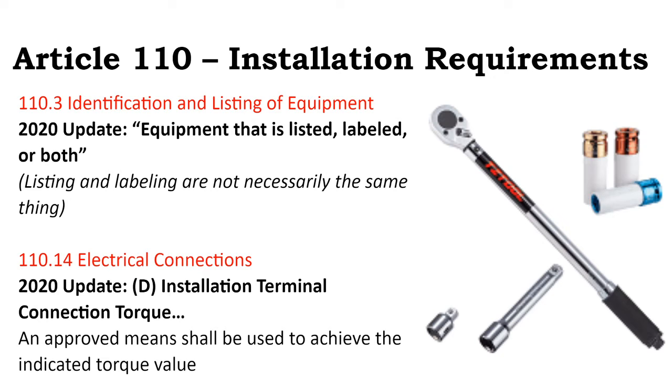Where that really gets you is, if you have underground cable splicing for inline splices, you may want to use those up on the rooftop in your conduit. You've got to make sure that the temperature ratings are correct. If they're not correct, an underground temperature rating might just be for 60 C and not 90 C, and if you put it on a rooftop, then it messes up your temperature calculations and you cause a fire. So, there's reason for this.